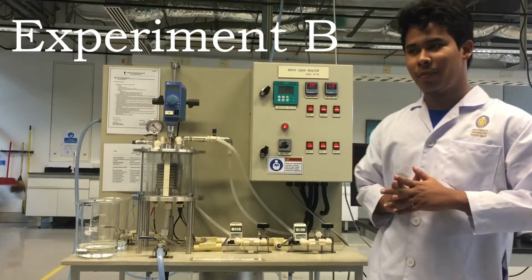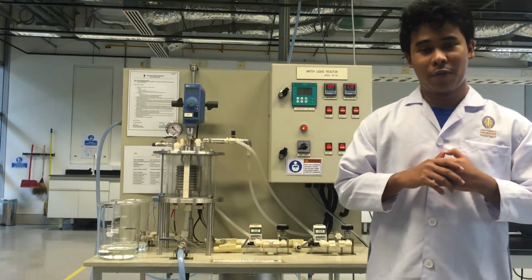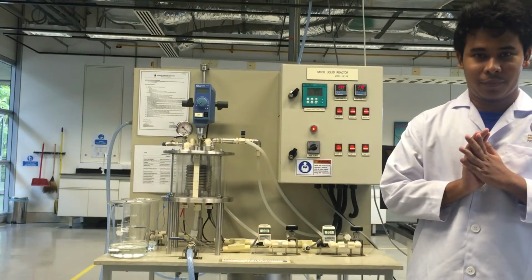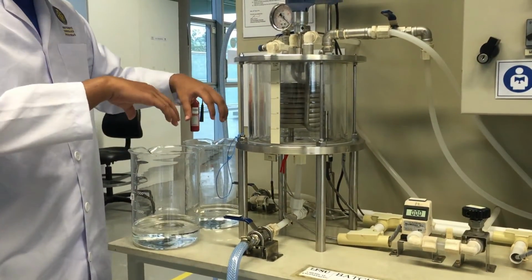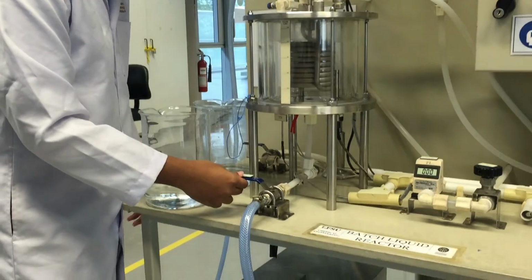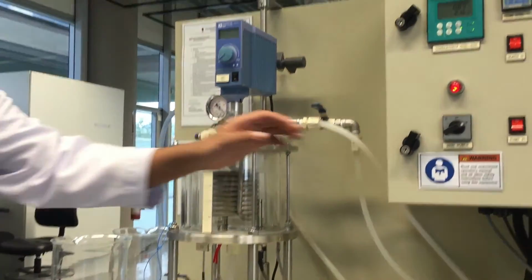In the last part of the experiment, part 2, we are using 1 liter of 0.1 molar sodium hydroxide and 1 liter of 0.1 molar ethyl acetate to undergo the saponification process. Before we add these two solutions into the batch reactor, we must first make sure that valve 11 is closed. Then we must switch on pump 2.